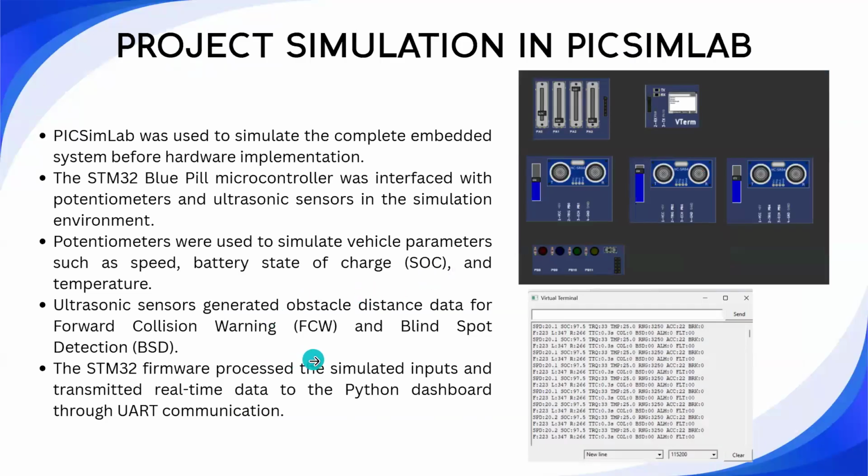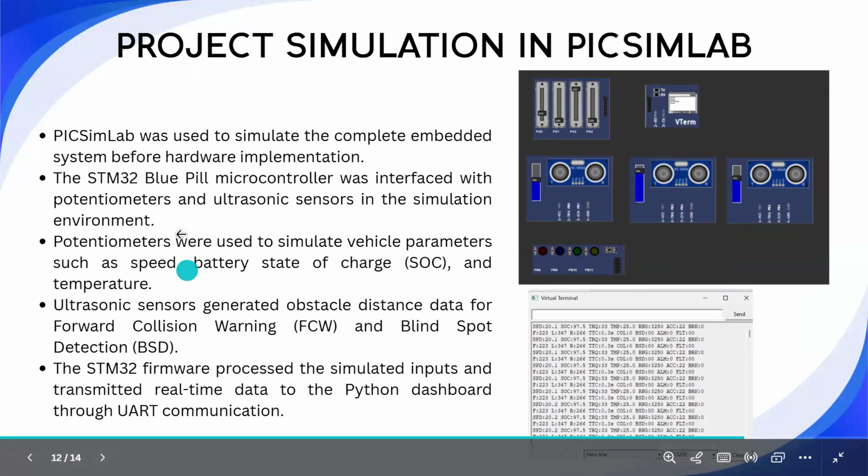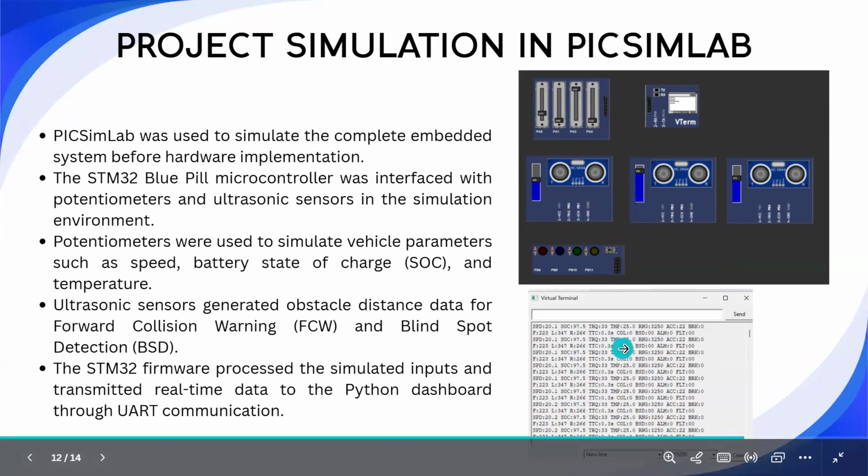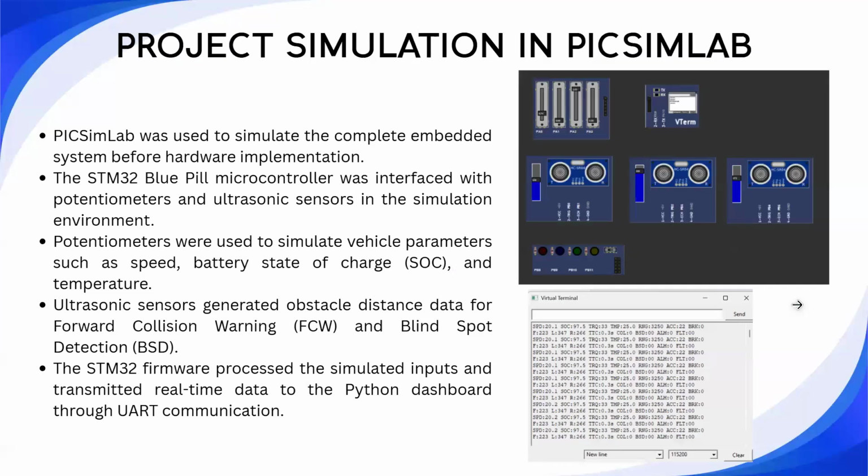Before implementing the project on actual hardware, the entire system was tested in the Proteus lab, which simulates the STM32 Blue Pill board along with the ultrasonic sensors and potentiometers. Changing the potentiometer values simulates changes in speed, SOC, brake position, and temperature. Obstacle detections generated by the ultrasonic sensors are processed by the Blue Pill board. And below are the terminal results which we found.